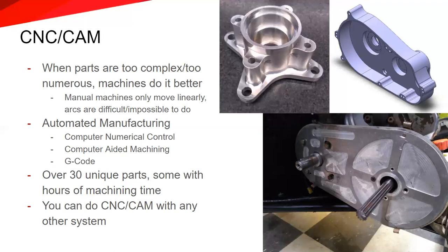Essentially, you take a CAD model and import it into this computer-aided machining program, and you simulate all the tool paths. You specify, oh, this has to be a 1/4-inch cutter, this has to be a spherical ended cutter, and then it'll generate the tool paths for you. What I mean by tool paths is generally just where the tool moves and cuts. If you take a look at the bottom right image, you can see a bit more closely the tool paths that are associated. You can see how in this large section there are kind of lines. That's basically the path along which the cutter traveled.